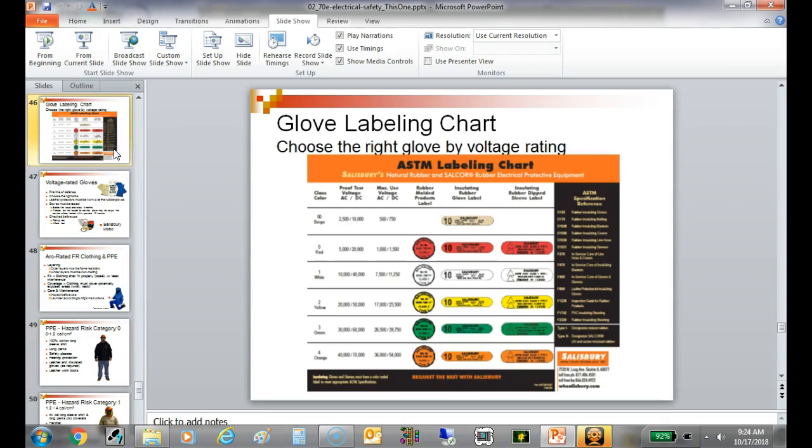Well, what it deals with is energy level. If I had a 600 volt supply that was fused at 1 amp, you would have to wear leather gloves, but you wouldn't have to have rubber on them. So it all deals with how much energy can get to you when you're out there, understand? There's a lot of math involved, and it's not only the voltage you're getting into, it's also what the protection circuits are that deal with it.